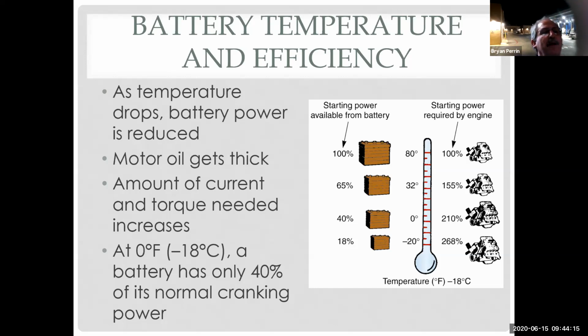Now, let's think about these numbers. This is using the right oil. What if someone uses the wrong oil in their car and they put an oil in that's thicker than it's supposed to be? Would that make this problem worse? Yeah. Absolutely. Isn't it interesting how something as simple as using a different weight oil, using a 5W-30 instead of a 0W-20, is going to affect how much energy it takes to start the car? That's going to have an effect on my battery.